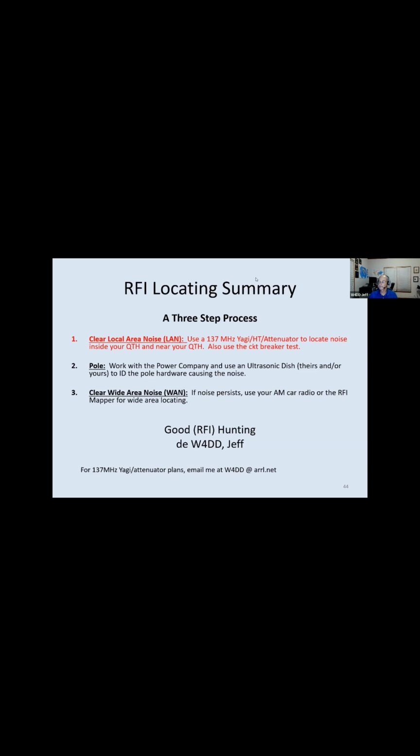Okay, got another question here at Coverly. We had a noise issue at Gail's house, and I thought it was the meter when I ran it down, and it turned out it was the bus bar in the box. When we replaced the bus bar, the noise went away. And then there's a device called a whole house line conditioner. Never buy a line conditioner that plugs in for a single device, but a whole house one costs about $100, and probably about that much more for an electrician to put it on.